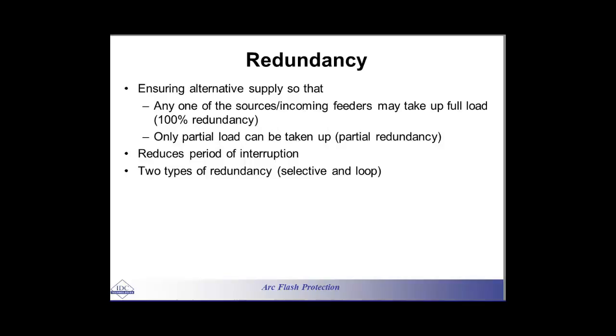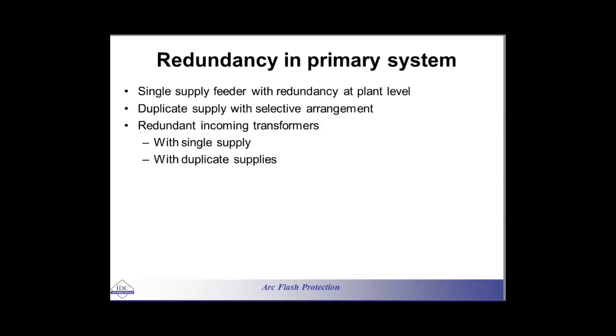Even at times they may decide to have two bus bars rather than one bus bar. So they may have some double bus bar, or main and transfer, or main and reserve bus bar configuration. So the idea is to have 100% reliability and redundancy if they can in their system. They have got many different ways to do that, okay? So redundancy in primary system, okay?